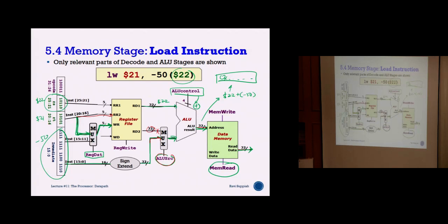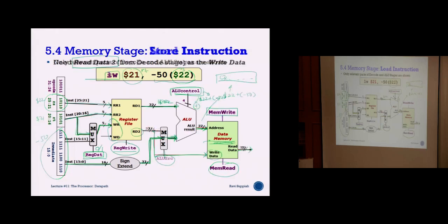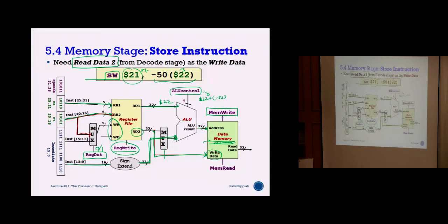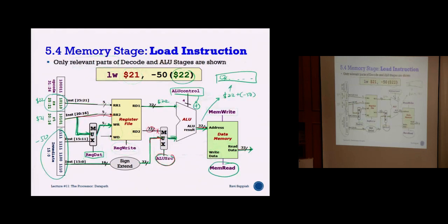So store word doesn't activate the register, right? No, because store word takes the data in the register already. How about load word? It also doesn't, because load word is to read from memory. So after I get the final address, I take from the memory, and then there's still one more stage which we will discuss tomorrow, that is the write back stage. But I said register, right? Yes, because load word is reading from memory and writing back to a register.